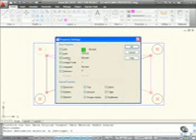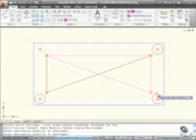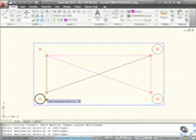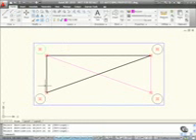And what I'm going to do is untick the layer option. I want everything but the layer to change. I want the layer to stay as layer 0, but the colour, the line type, line weight, and so on, all to be the same as that circle there. So if I OK that now and select my destination objects, like so, look what happens. If I now enter there to finish, look.